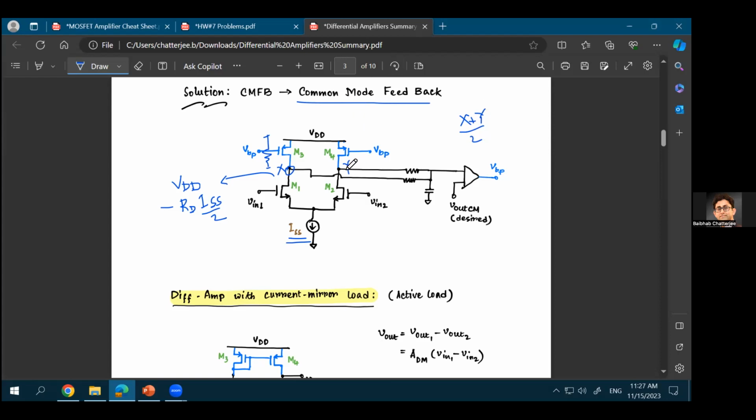In case of analog circuits, how do you take the average of these two quantities? You connect them, tie them up at the same point, right? You short them so that whatever interaction can happen between the two points can happen, and then eventually they will figure out an intermediate point between the voltages X and Y.